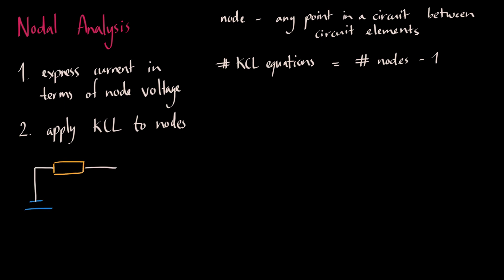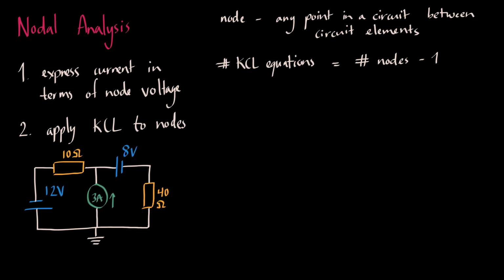Here is a basic circuit incorporating two voltage sources, a current source, and two resistors. We can see there are three separate nodes with unknown voltages A, B, and C, as well as a fourth reference node connected to ground. Also note the orientation of the voltage sources. Node C is an example of a supernode, which is a node adjacent to a voltage source. That means we can find its voltage immediately.